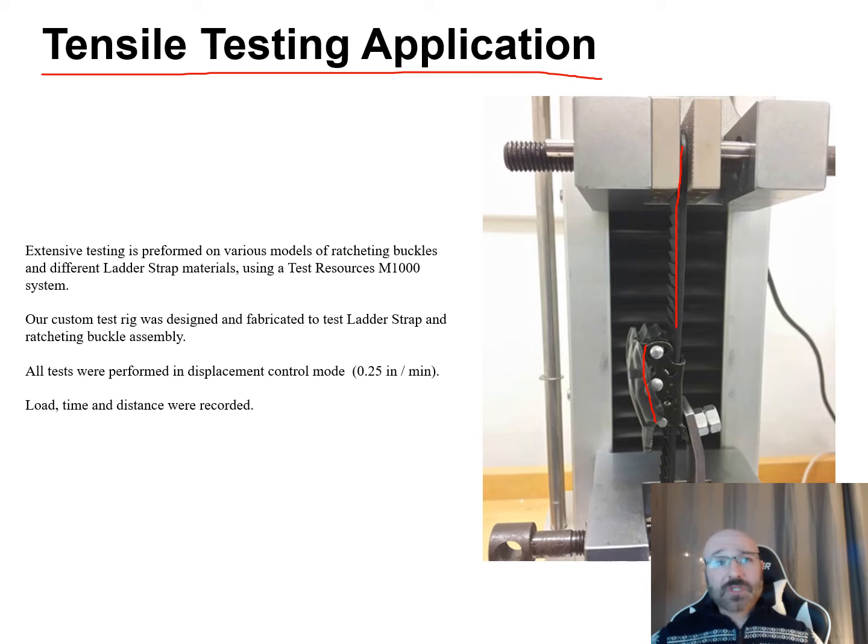And for this particular project, we were looking at different materials and seeing how they would hold up. And we were really interested in, what is the max load? Where does failure occur? And not only at what load or stress does failure occur for these, but also what is the deformation at that point? And what is an acceptable deformation? Do we want something that's more elastic and more ductile, that's going to stretch a lot before it breaks? Or do we want something that's going to not really change length much, but then could have a catastrophic failure and break?